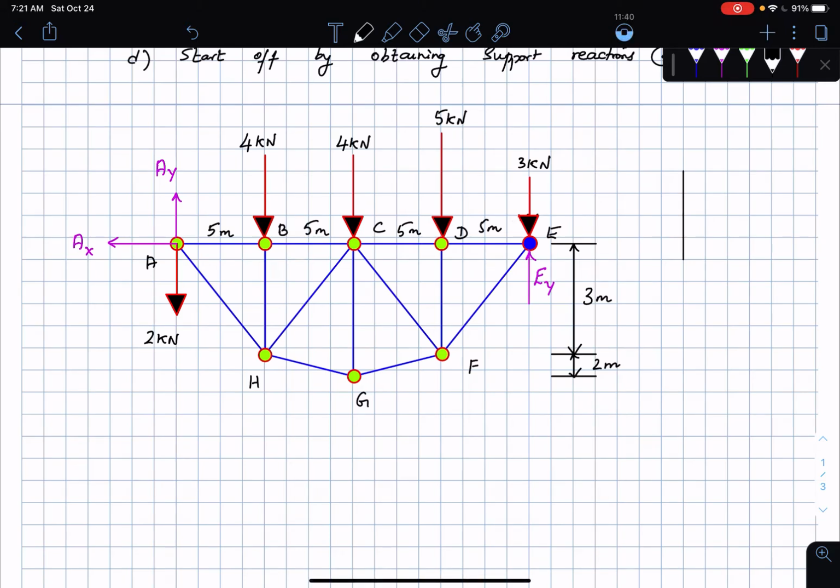This is the part of the problem where you need to be quick, okay, to find the support reactions and so on, because these are things that are fairly straightforward, and it comes through practice, of course. All right, so I'm going to do the force balance equations. I can directly find out that AX is equal to 0 if I sum forces in the X direction.